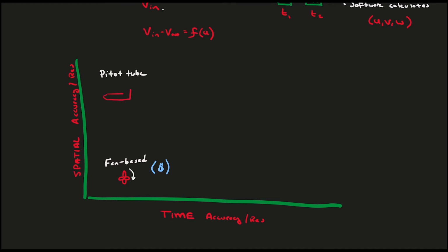Next, the pitot tube can have a much finer spatial resolution. However, pressure transducers are still limited in time resolution, so it cannot get you data at a particular instant. These are slightly more expensive and can run you a few $100s at most.